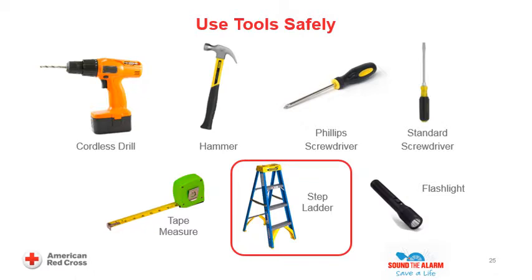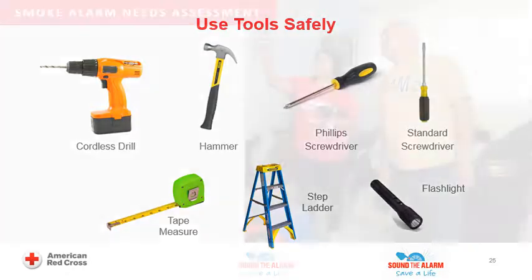Do not use ladders in passageways, doorways, or other locations where a person can hit it. Set up suitable barriers. Do not overreach. Move a stepladder when needed. Do not shift or walk a stepladder when standing on it. Please alert your event leadership if you have any questions about these safety protocols. Please know that in the event that you are not comfortable with performing any of these safety protocols, a different in-home visit team role can be assigned to you by contacting your event leadership.